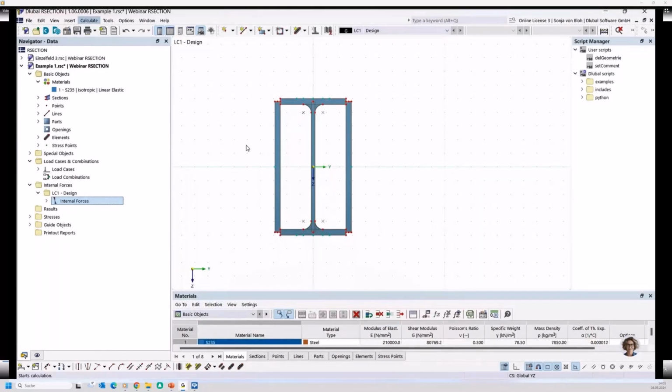Design using the plastic cross-section resistance is an essential aspect for efficient steel structures. Eurocode 3 provides solutions for combinations of internal forces only for specific cross-section shapes. The plastic cross-section resistance, considering various combinations of internal forces, can be determined in our section using the simplex method.